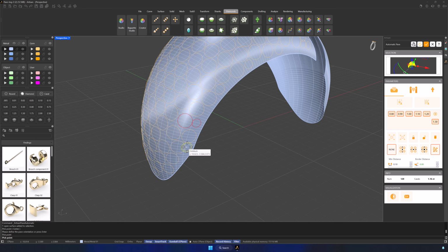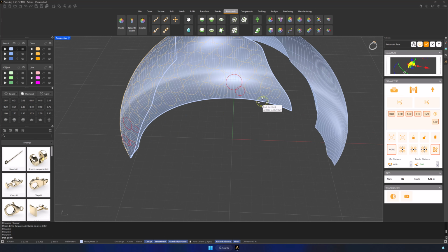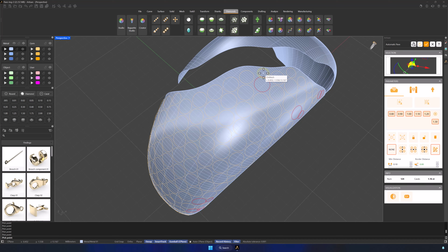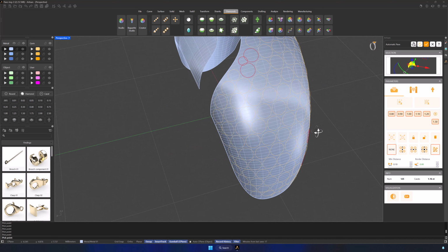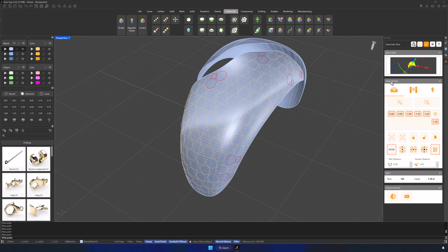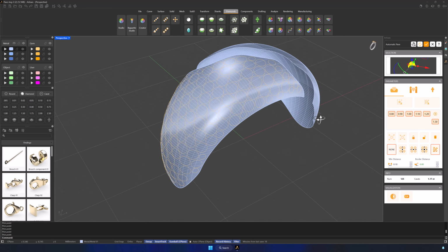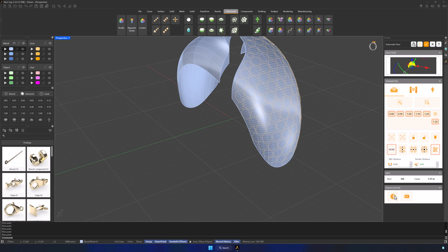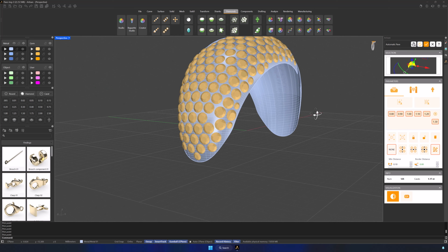Now, fill in some empty areas, select the size, and add the gem. It may appear in red, but we will recalculate it later. Press Compute until all gems are correctly positioned. Display the gems for final adjustments. Remember that you can move, add, and resize any gem at any time and recalculate to reposition them. You can also lock gems if you believe their position is perfect. When you recalculate, they will remain unaffected while the rest adapt to them.